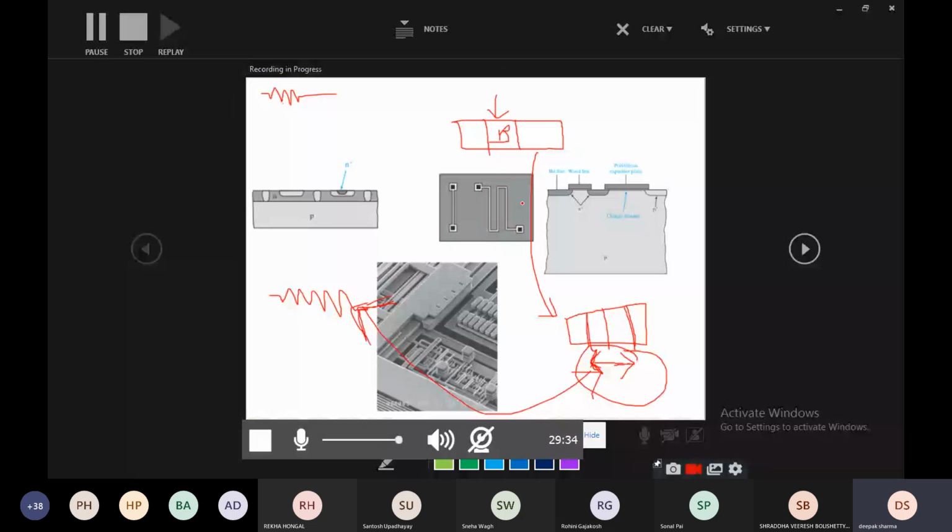Alternatively, a p region can be made during the base implant, and an n-type resistor channel can be included within the resulting p region during the emitter implant step, right?